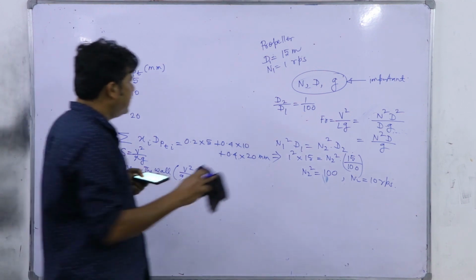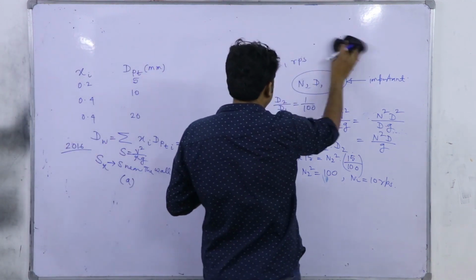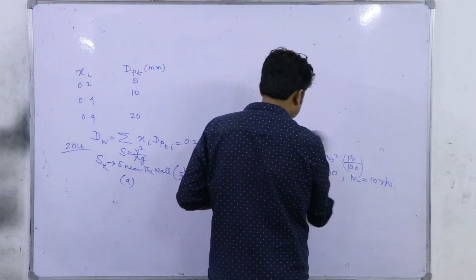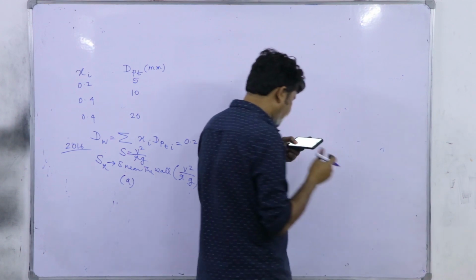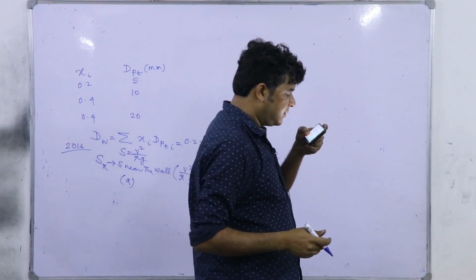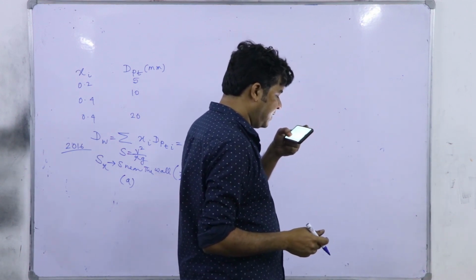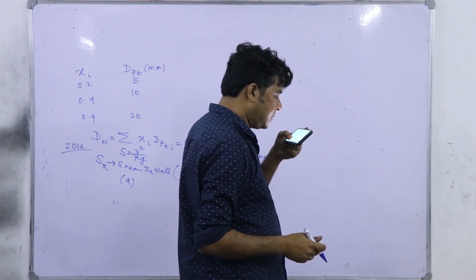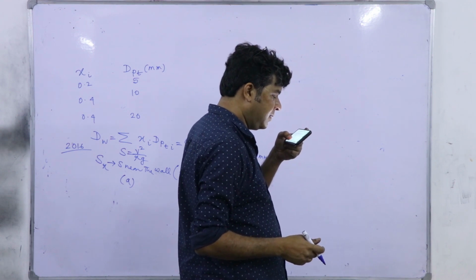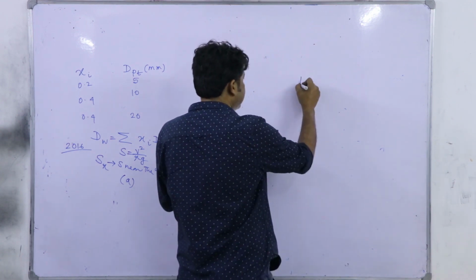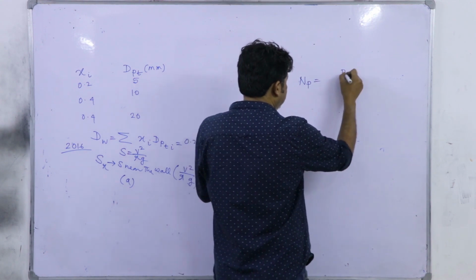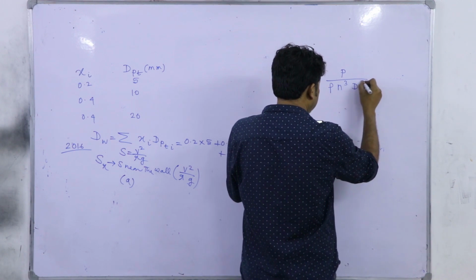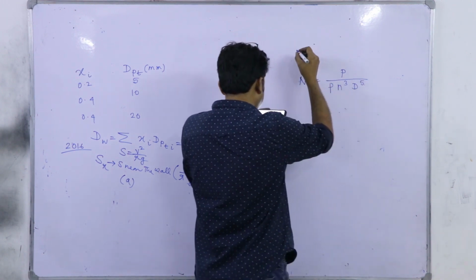So, mostly we can see that problems will be either from filtration, or from crushing, or from scale up related to agitation and mixing. Another scale up problem. The agitated cylindrical vessel is fitted with baffles and flat plate impellers. The power number of the system is given by Np, which by definition is equal to P divided by rho N cubed d to the power 5.